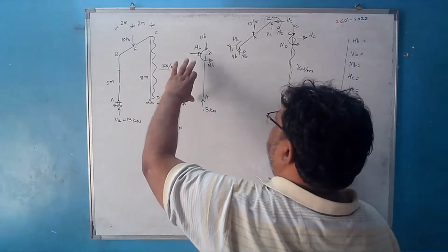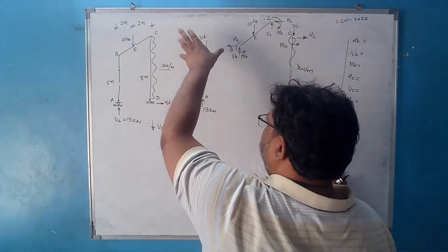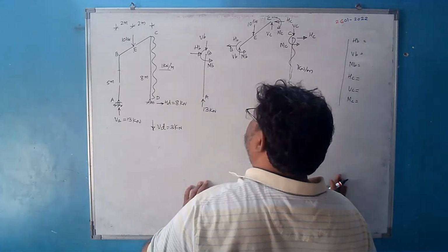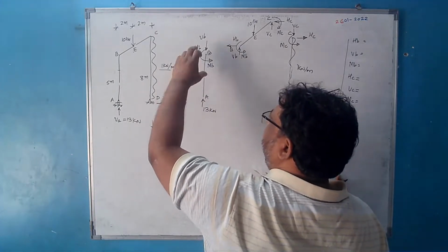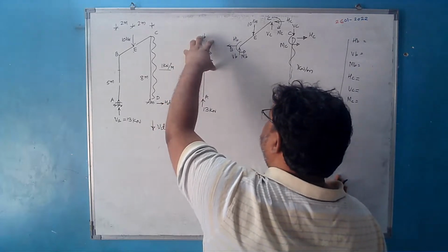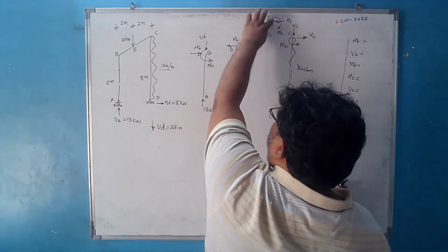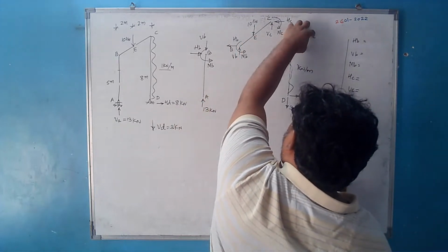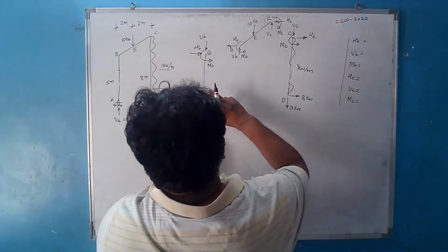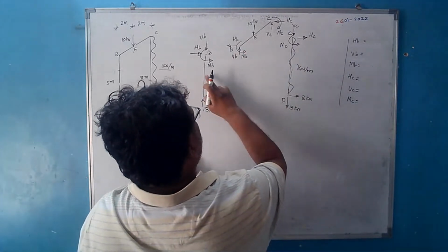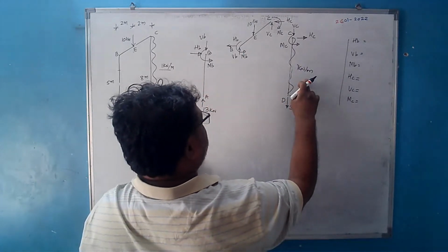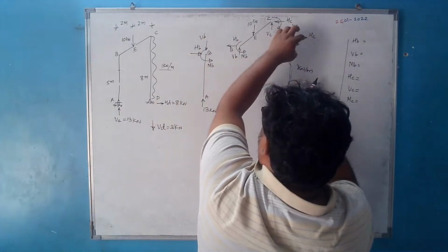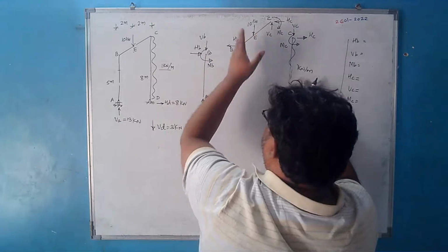I will prefer to take vertical or horizontal members wherever possible, where the unknowns are fewer. If I see this member AB, there are only 3 unknowns. If you see this system, there are 6 unknowns here. If you see this vertical member, again there are only 3 unknowns. So rather than taking this vertical and inclined, I will prefer to take these 2 vertical members to solve, so that I will get the required unknowns. If I know these, we can get the others.